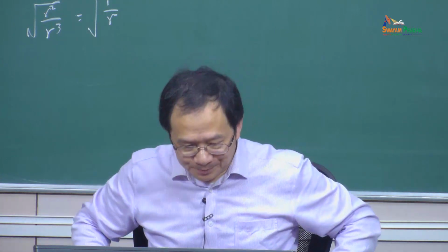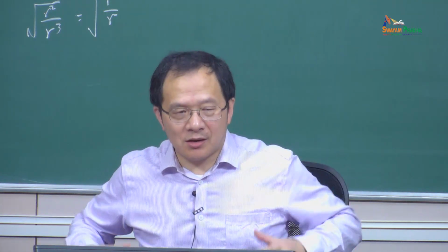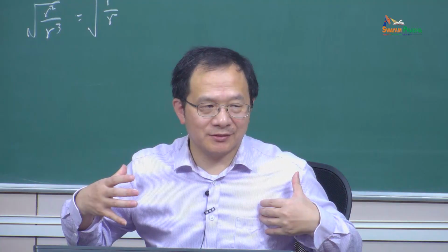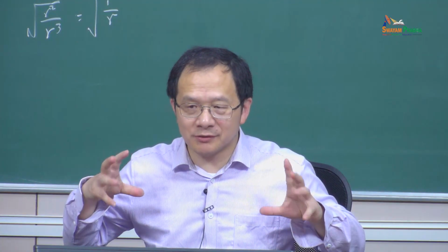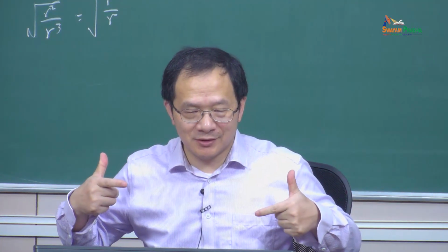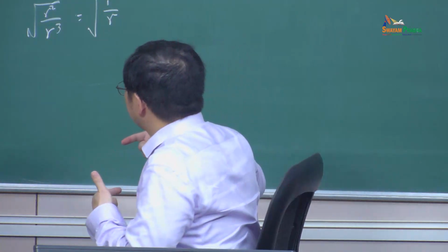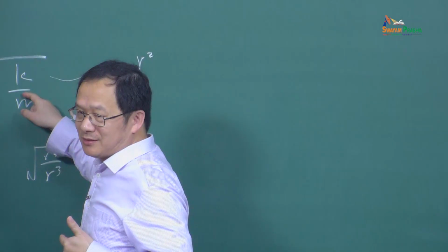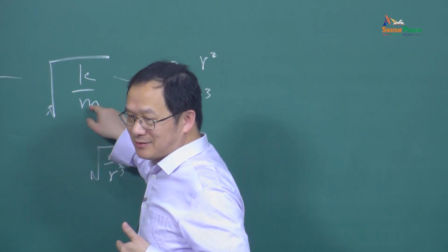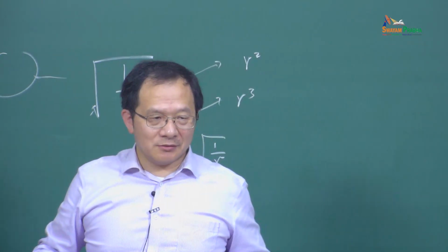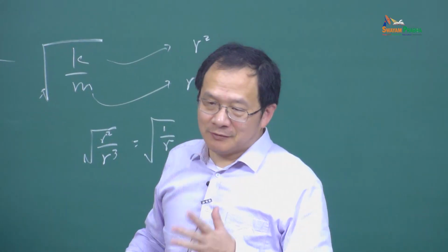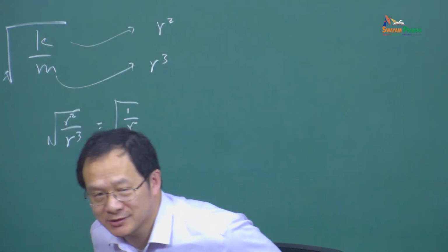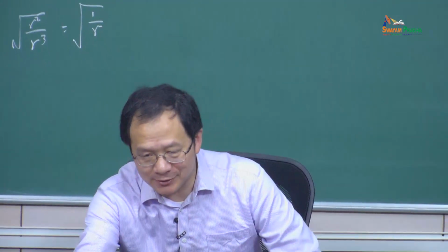What can you do? Now you want to reduce the vibration frequency. You reduce that, right? You reduce the stiffness, then you increase mass. Now instead of using physical mass increase, we can use added mass.